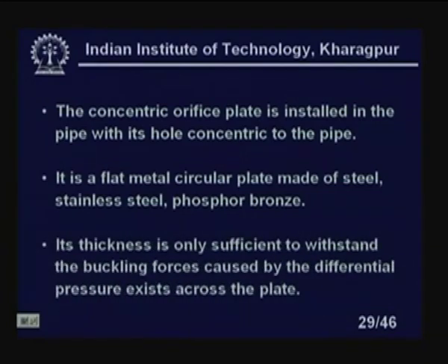Its thickness is only sufficient to withstand the buckling forces caused by the differential pressure existing across the plate. So as long as it can withstand that differential pressure, you can use a thin plate, but it should not buckle, otherwise the entire calibration will go wrong. For that reason, if you have a larger differential pressure, we have different types of flow measurements, although that basically depends on the differential pressure measurement.